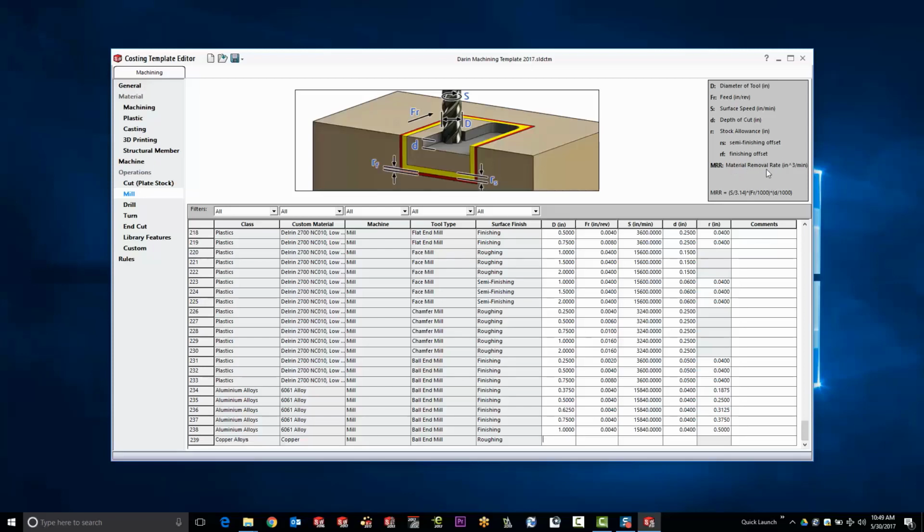It's all about material removal rate. So unlike a machining product that's actually doing tool paths and passes, this is just trying to figure out how much material it can take off of the part at any given time. So it becomes a process of elimination with the costing evaluation, where it's determined based on the stock material we're beginning with and the finished part that we're ending with, and the fewest amount of operations that we can actually remove that material. So the formulas are listed specifically for each type of operation.